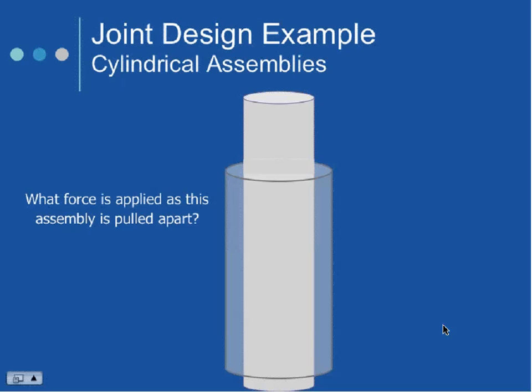Primers. Primers can help. They can definitely help with our cyanoacrylate, right? What about plasma or corona, right? That raises the surface energy, which we'll look at. Or what about adding a chamfer right up here and increasing that surface area, right? Anytime you increase the surface area, a lot of times you'll see your adhesion go up.